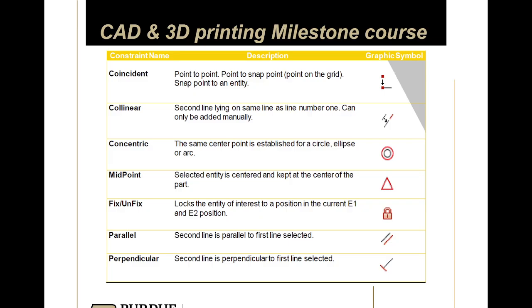When you want your design to be nice and precise, locking in an arbitrary constraint isn't best practice. Usually there is some way to define your lines, arcs and points with the rest of the constraints to make it fully defined, so you don't need a fixed or unfixed constraint.